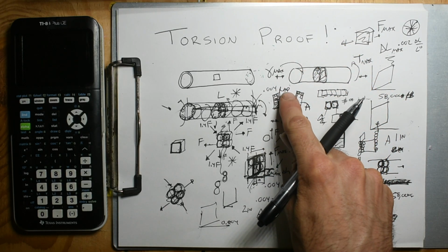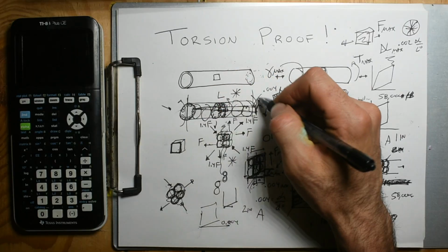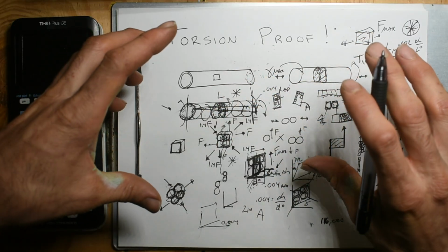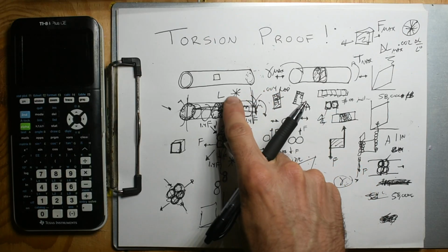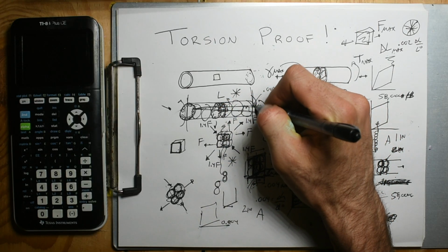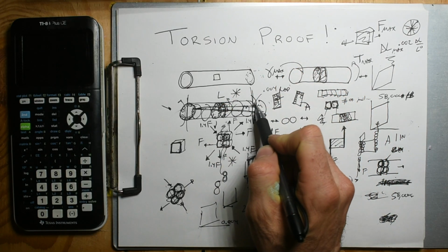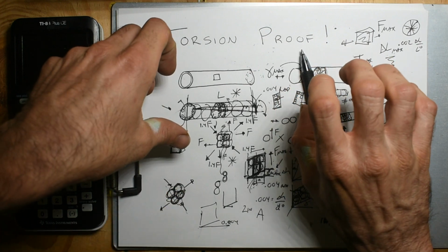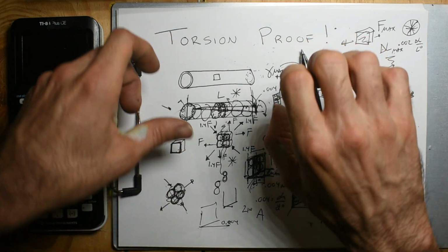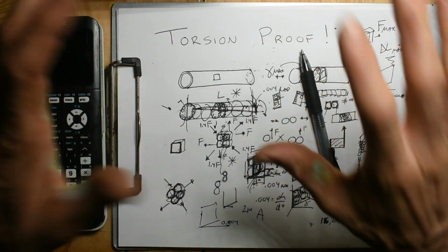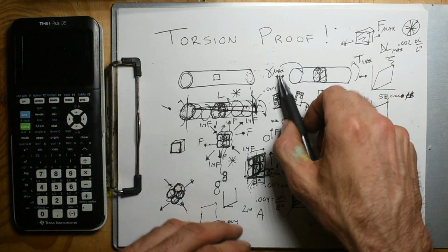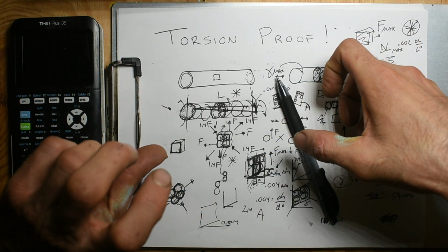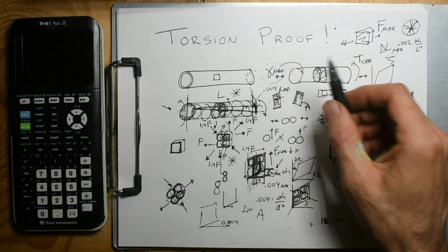So 0.004 radians times the length of whatever bar you're torsioning. 0.004 times that length is the arc length from this angle, which is how much the bar can tweak, and then you can let go, and it's going to be right at the top of that linear range. But if you go any farther, it's going to plastically tweak out. So that's where that max comes from.